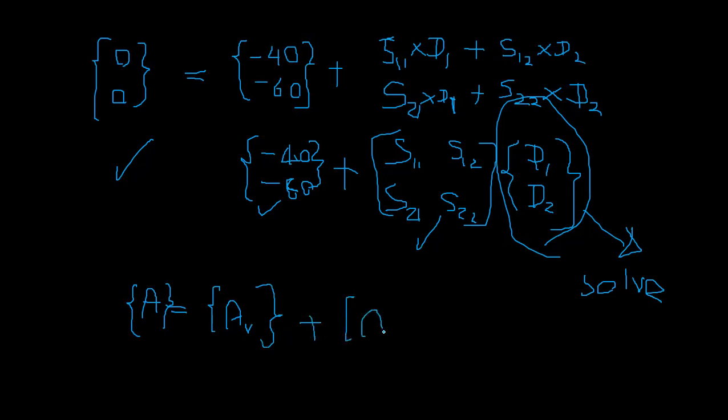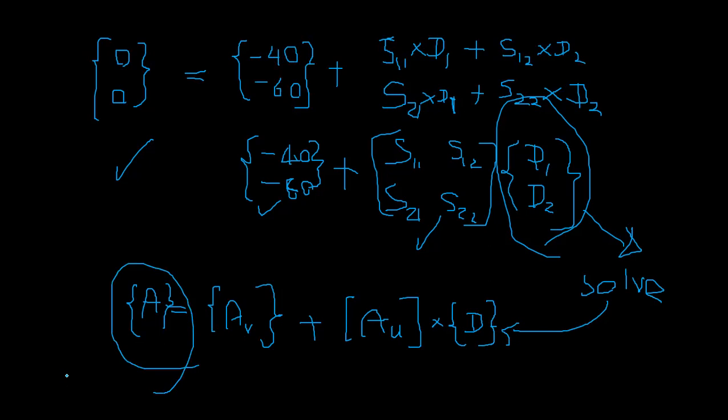And the unit actions into the displacement matrix. You solve this and you plug into this and find this one, the member forces, right? This is the displacement at that joint A. So I need to find these stiffness values. For that, I'll consider a table.